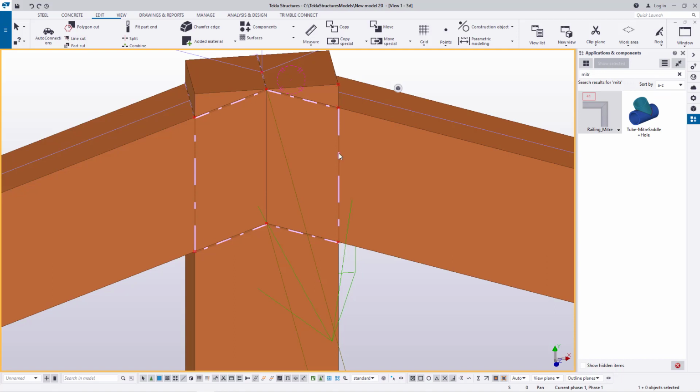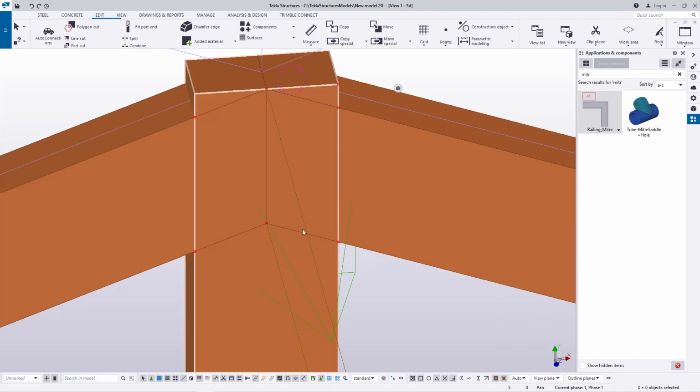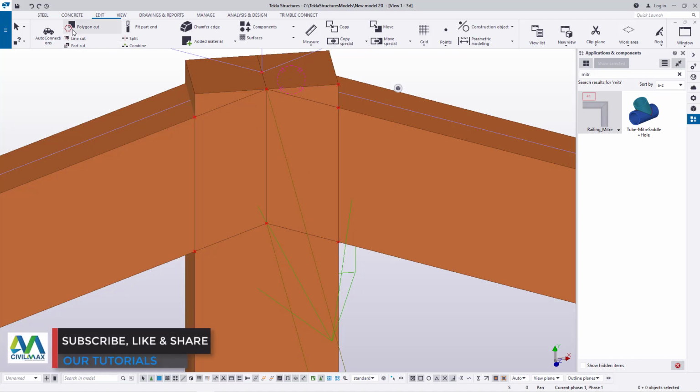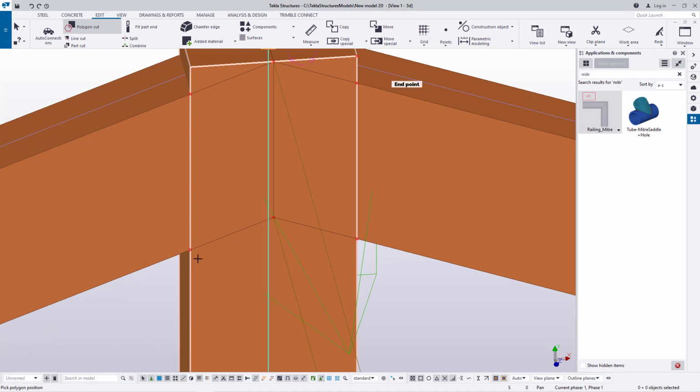The option we took was not appropriate, and we are going to take another one that will work perfectly. So I'll come here and click undo to bring that component back, the component that we trimmed off by mistake. And we'll come back to edit and click on edit and come to polygon right here. So I'm going to select this component here and start defining the parts I want to trim off. So I'll start my point.